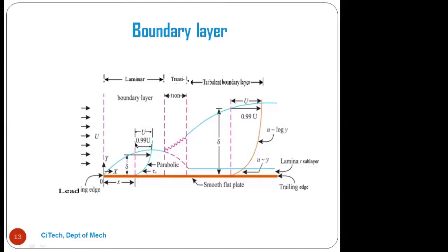Up to that point we are considering it as the boundary layer, understand? So I think you understood, okay? The distance perpendicular from the plate, where the velocity of the fluid approaches the mainstream velocity, up to that distance is called the boundary layer thickness, which is denoted by delta.